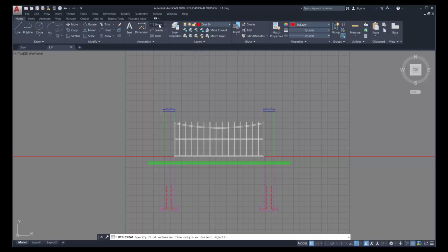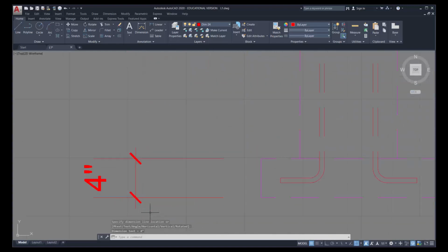We'll click on that. Now the object snap setting is already looking for intersections or endpoints. I'm going to click on this part of the footing, the lowest part, and then move upwards to the second part of the footing and stretch my dimension out and click. Let's zoom in on this to see what we've actually done. There's all the adjustment values that we did. Provide the dimension line. There's our extension line.